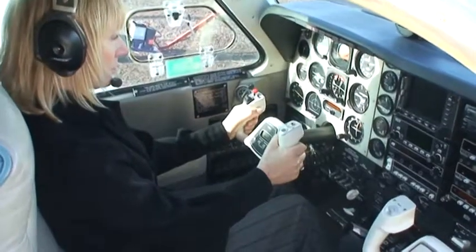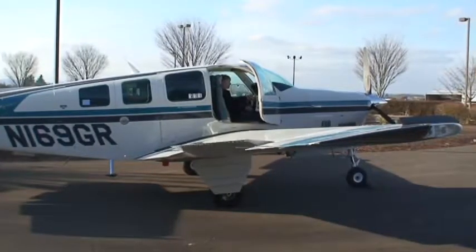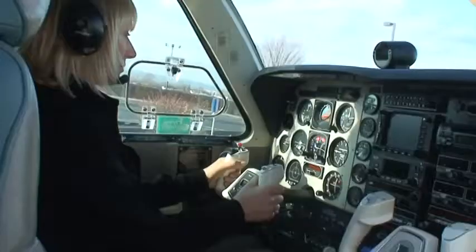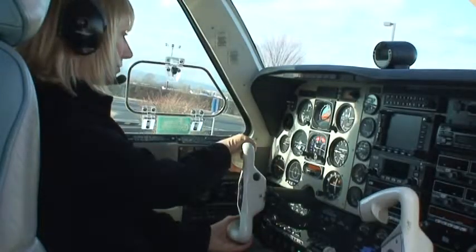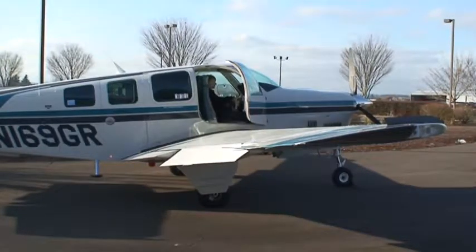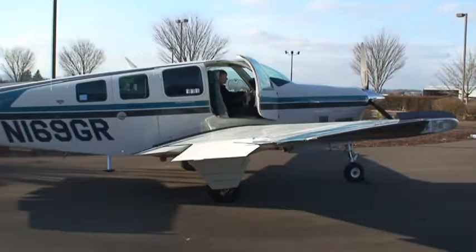When the right aileron goes up, air is deflected up, and that pushes the right wing down. This turns the airplane to the right. If you want to turn the plane to the left, rotate the control wheel or the stick to the left. This moves the left aileron up and pushes the left wing down. This causes a left bank or a left turn.